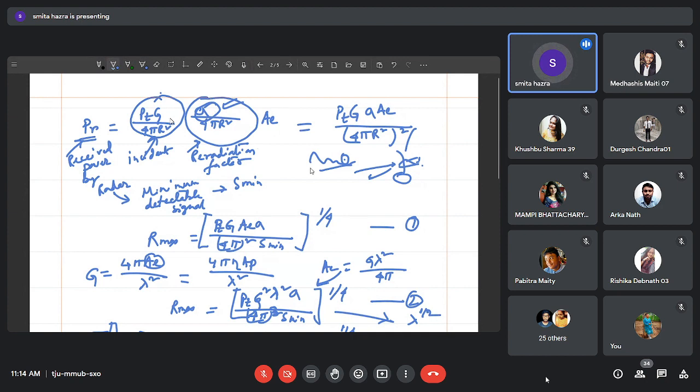And suppose we get it from a flying bird, then based on the nature of the feather, we will get very weak echo signals. And not only that, it matters from which portion of the bird we are getting the echo, whether it's from the beak portion, tail portion, or belly portion. Based on these things, we are getting a projected view. And summing up all the projected views, we can get a picture, maybe a figure like this, from where we are getting these sigma contributions. So modeling of sigma is a very crucial factor.